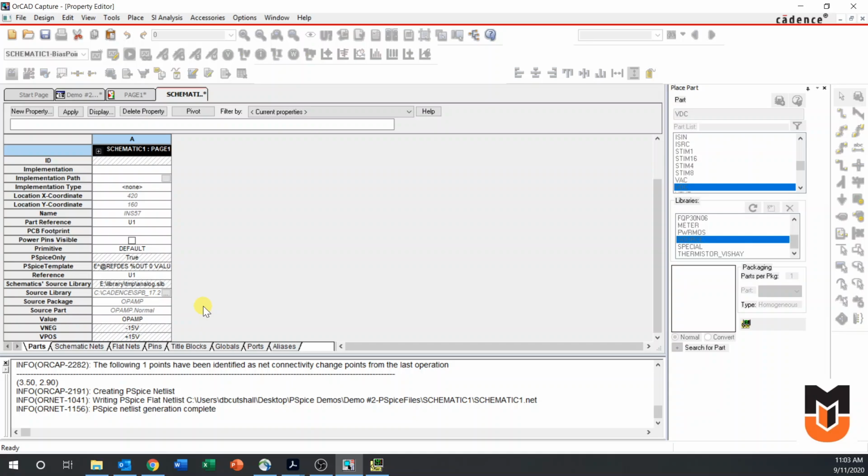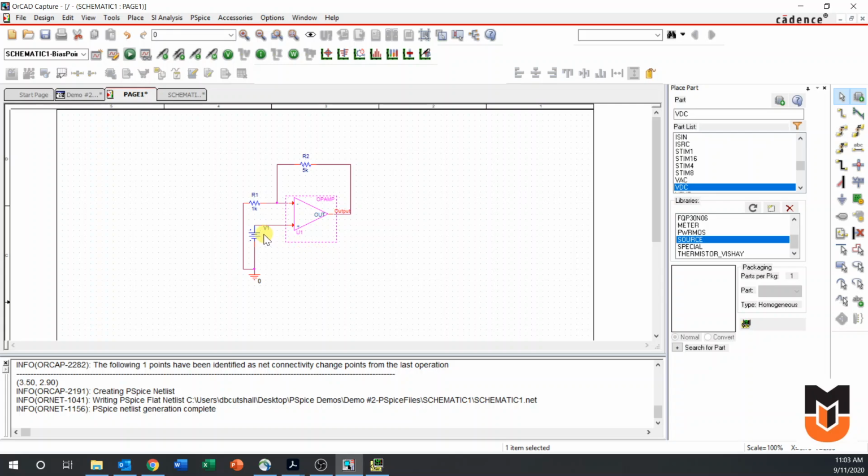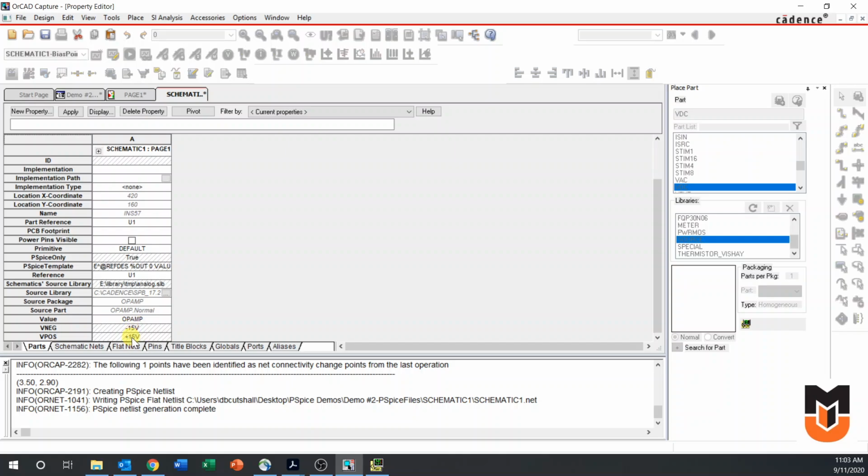Because this is just a simulation and we're not worried about the power or affecting the devices, we could either come in here and increase these voltages, or if we come back to our circuit, we could also decrease this input or change this gain. One note about increasing these voltages: you want to be careful not to exceed the specifications given for the particular op amp you're using.